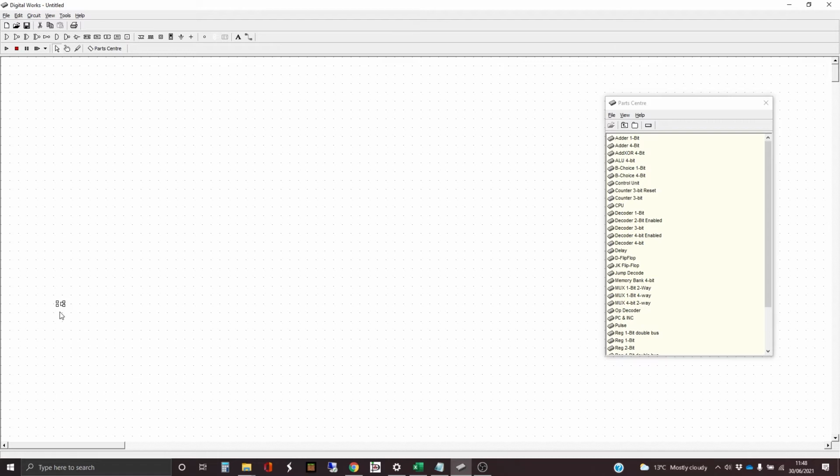the bottom. And to start off with, on the left-hand side, I'm going to have output enables that can go to the various registers. And on the right-hand side, I'm going to have bus reads that similarly can go to various registers. And I'm going to stick an LED on this. I quite happily tend to connect a tag to an LED, even if you're not going to ever see that LED. It's kind of nice to know it's there in case we have problems later down the line, and we want to be debugging what's going on. We can dive into the macros and see the status of things using the LEDs.